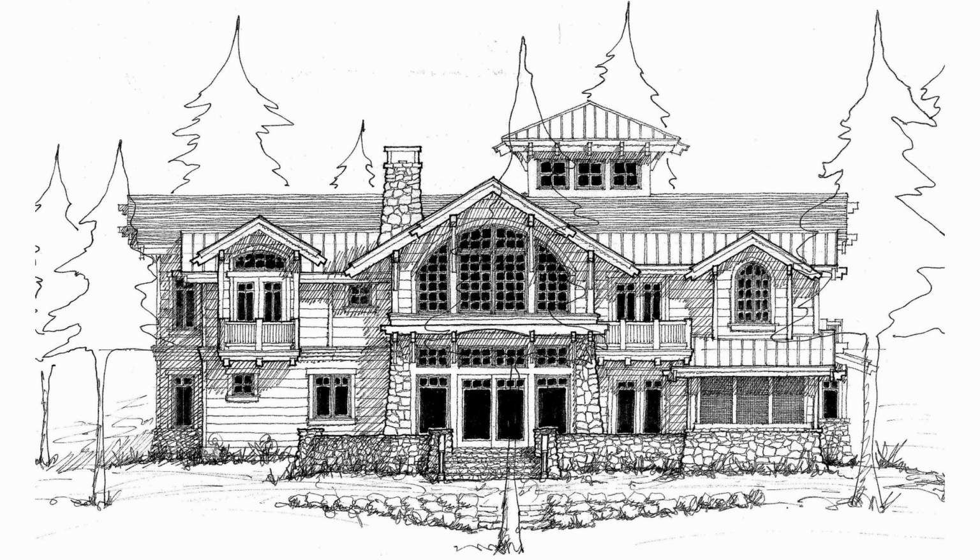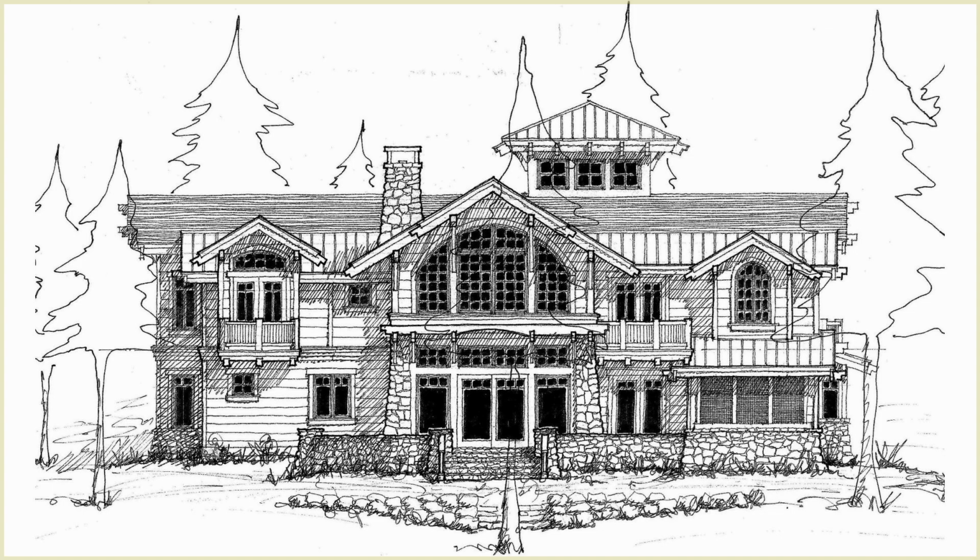It's another example of a hand-drawn elevation. Same sorts of things that we're going to see. The thickest, boldest lines are the pieces that are closest to us, and the thinnest lines are the ones that are furthest away. The other thing that can happen with some of these, and I think this is a good example of it, is this particular architect was trying to tell you that this building was in the middle of some trees. And so you can see the squiggles that represent the trees along the sides and that sort of thing.